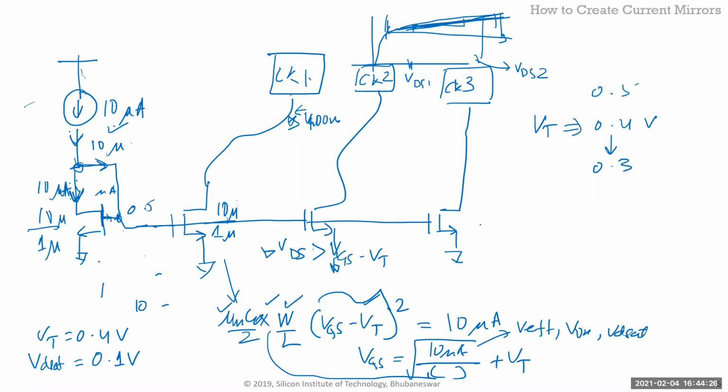So for example, let's say the VT is now 0.5 volts and VDsat is still 0.1 volts. What is the VGS needed to create 10 microamp? 0.6, right? In the resistor case, it was still 0.5, or maybe it was lower because of the resistor. So I would have a huge error because it's 100 millivolts squared times mu n Cox W over L. So it's a huge error, right? But now this will automatically make it 0.6 because that guy's VT is also 0.5 right now. VDsat is also the same because they're the same size, almost close by, and then they will be fine.